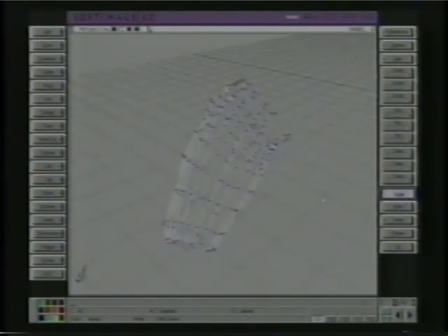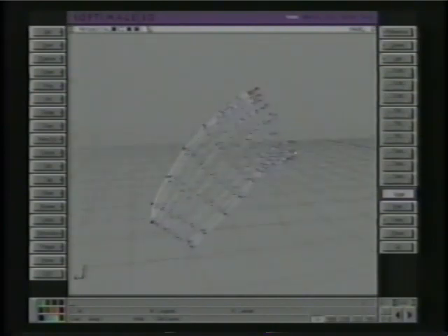From here, save it out as an IGES file. Once I digitize all the splines in the arm, for instance, or any given section that I'd like to digitize at the same time, I save it out as an IGES file and bring it into Softimage. Now here are the curves after being translated in Softimage. This is what they come in looking like. It won't make a model file, it'll make a whole scene file, and this is how it comes in.